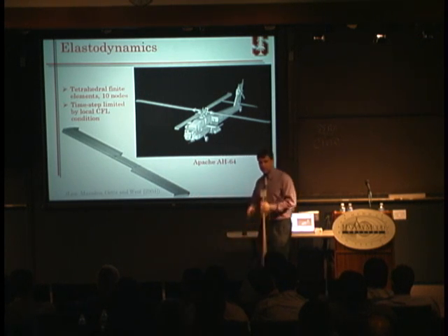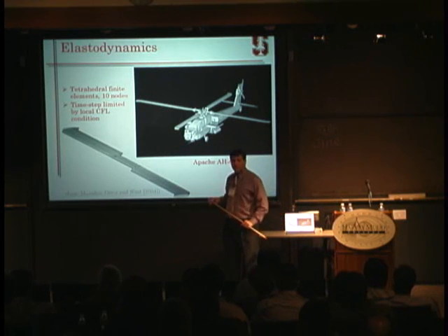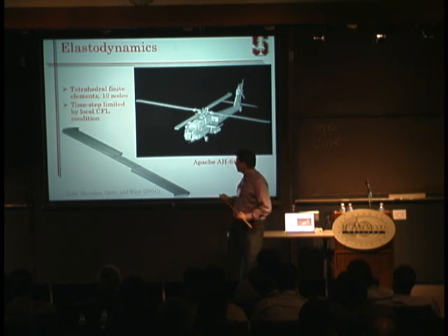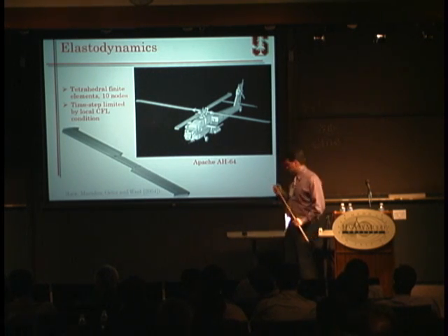So we simulate here the dynamics of the blade of an Apache AH64 helicopter using tetrahedral finite elements with 10 nodes. These are quadratic, piecewise quadratic inside each element. And we choose the time step of each element using a Courant-Friedrichs-Lewy condition, CFL condition. Okay?